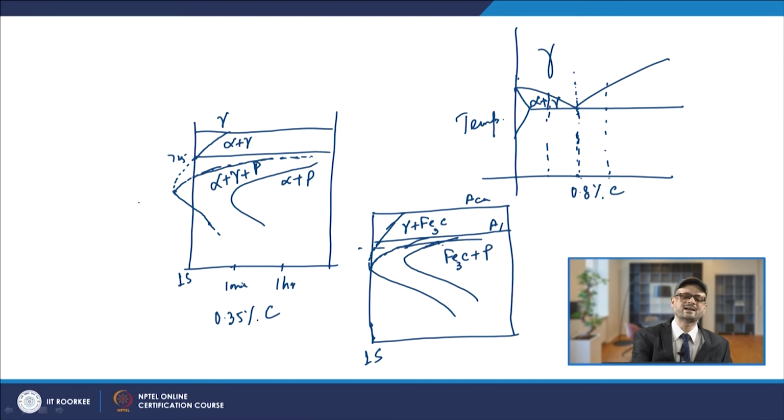So, in this case, hardenability is less. Your chances of conversion to martensite become less because you have to apply a very high cooling rate, and only then you will get the whole martensite. Now, how to change this hardenability? So, basically, with the use of alloying elements you can very well change the hardenability, and you can have the conversion to a full martensite structure.